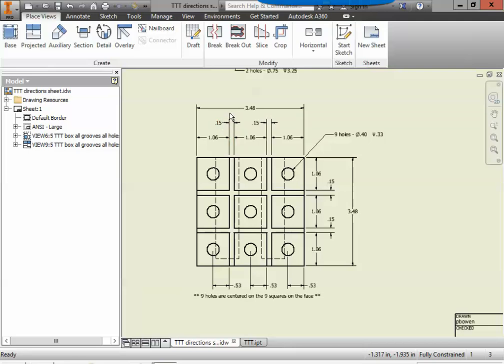The groove, however, does not have an overall length. For this, we need to imagine this groove as acting like a knife to cut into our wood. It doesn't matter if the knife is longer than our piece of wood. It would matter, however, if it was short. So we're going to make our groove 0.15 inches wide and longer than our part.